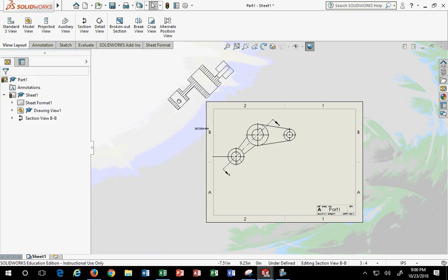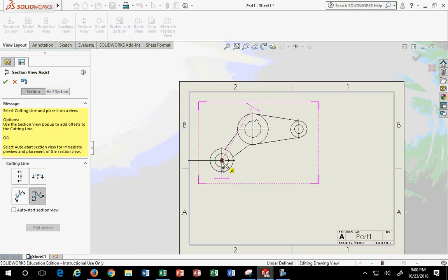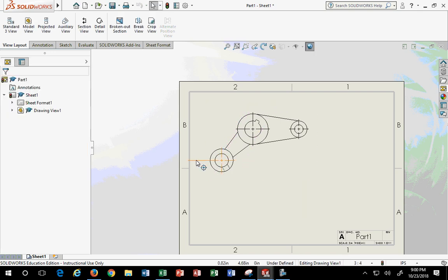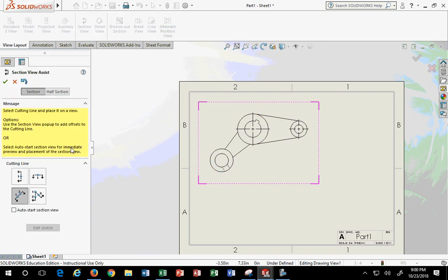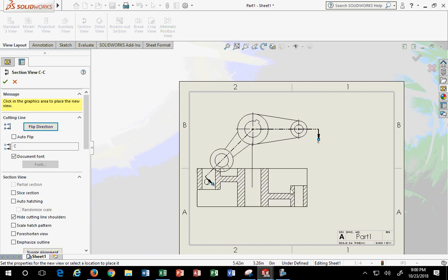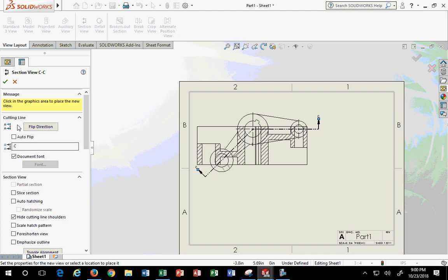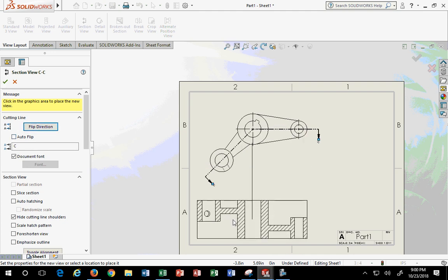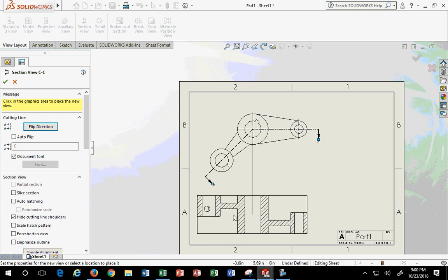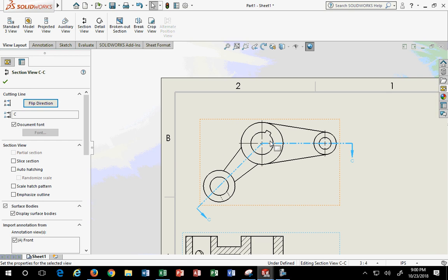I would accept the reality that when you do the aligned sectional view, you are going to have to make, whoops, wrong center, excuse me for that one, a decision how you want to show your object. Do you want to show it this way? If you show it the other way, you're losing the hole. So I do recommend that you do it the other way, and you actually flip it, so you see the actual hole. Either way, you're missing the key, because the other way doesn't make the key look any better. The keyway, all the information on the keyway, to be honest, is up here.